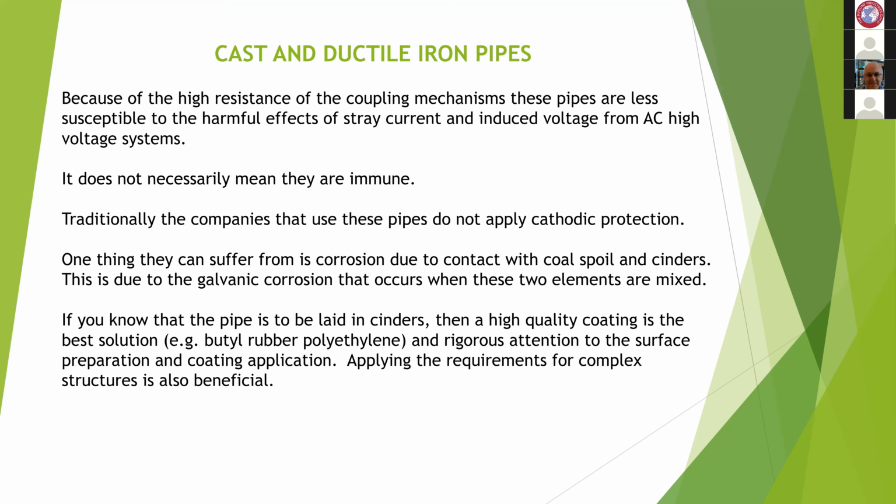It's mainly because there's a high resistance in the joint couplings, and that prevents the flow of voltages and currents through these short lengths. They're not an attractive path for the stray currents, and also they don't have the high voltages induced in them, because you need a long length to get the high voltages induced.